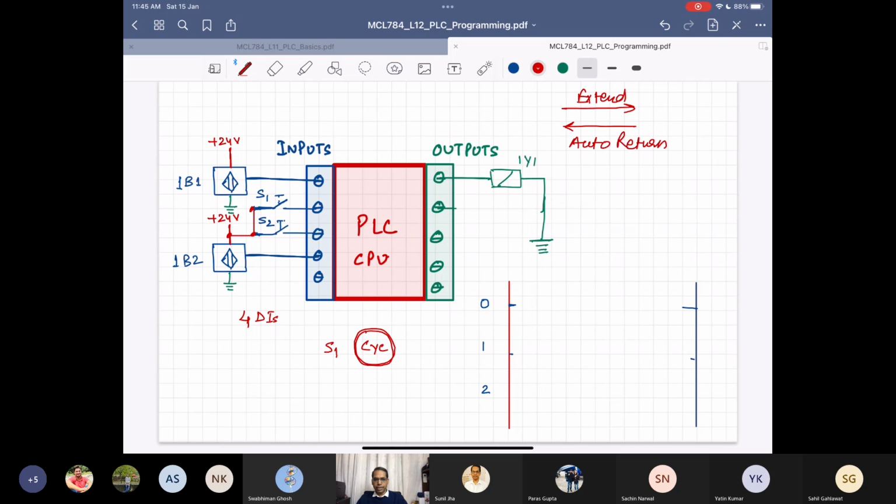So I need not control the retracting motion through manual intervention. There are many operations in the industry where you give some input, then the operation happens and the cylinder goes back. Maybe punching, maybe sealing. There are many functionalities you can implement this way. So whenever S1 is pressed, S1 on, and you release it, the cylinder should extend and then automatically retract.